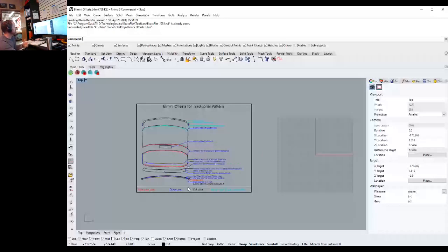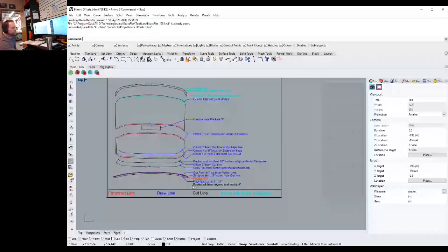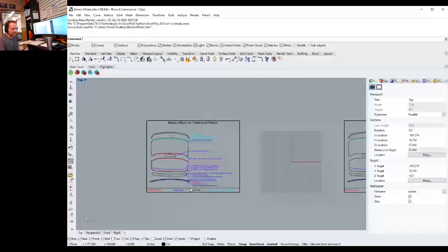So this bimini cheat sheet is, when you're doing CAD, you need to know that you offset this line to that distance. We measure it to the center of the frame, let's say. So the offsets for us, if you're on mid bow, would be just a half inch for seam allowance, right? But you need to know that when you go in here.